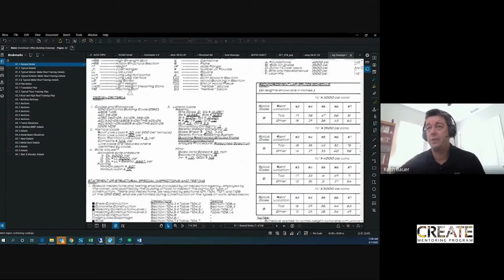We'll also show design criteria. This is required by the code, that we have to say what kind of loads we're designing to. I don't think there are any questions on this in the scavenger hunt, but it's useful to know that roof live load, that's for people walking on the roof, is designed for essentially 20 pounds a square foot.